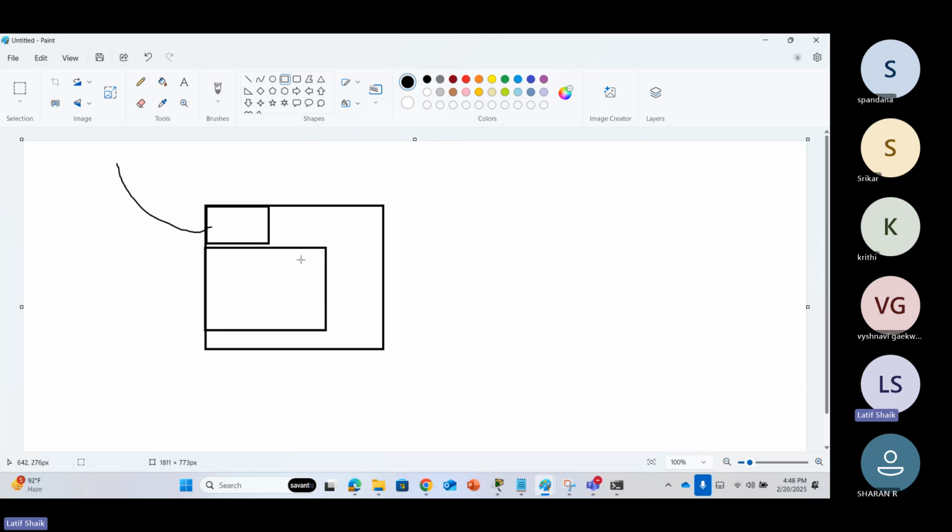Right. And this is the SMPS to motherboard power connection, the CPU power connection, like that. See the power connectivity first. And from here, the front panel power button connection, up to only power. Next is the main power supply. Okay. You press the power button and the system is not powering on.